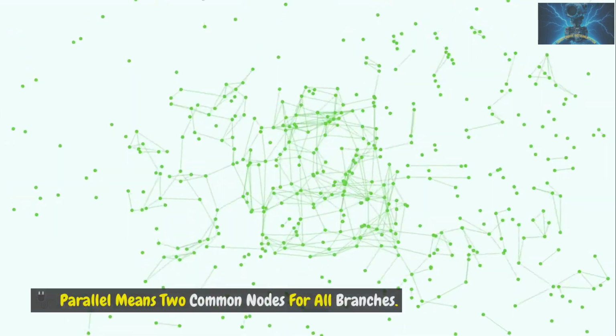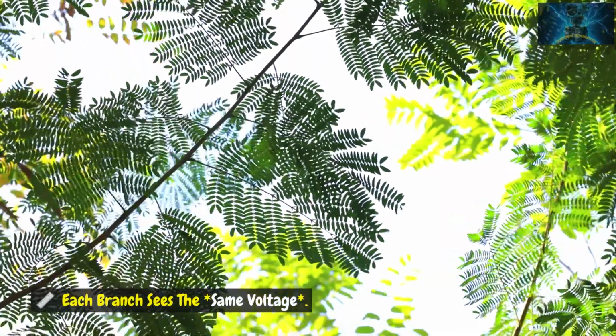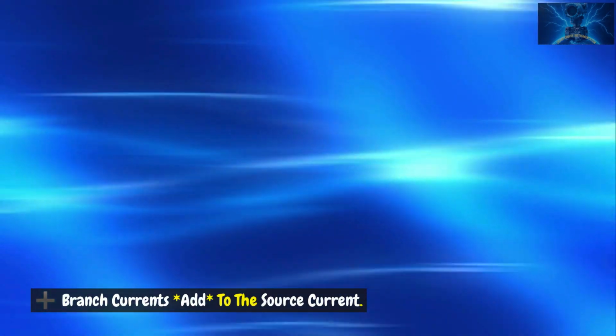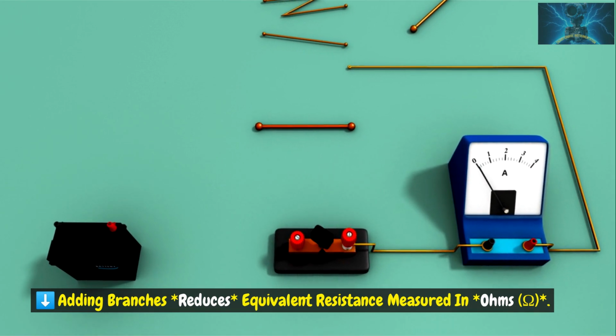Quick recap. Parallel means two common nodes for all branches. Each branch sees the same voltage. Branch currents add to the source current. Adding branches reduces equivalent resistance measured in ohms.